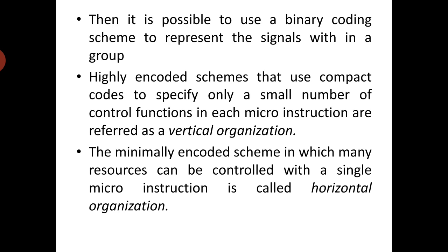These all come under another group. Any one of these can be selected by a unique 4-bit code. Why? Because here we have a total of 9 control signals from PC out to the temporary register, and these 9 control signals can be represented by using a 4-bit code.